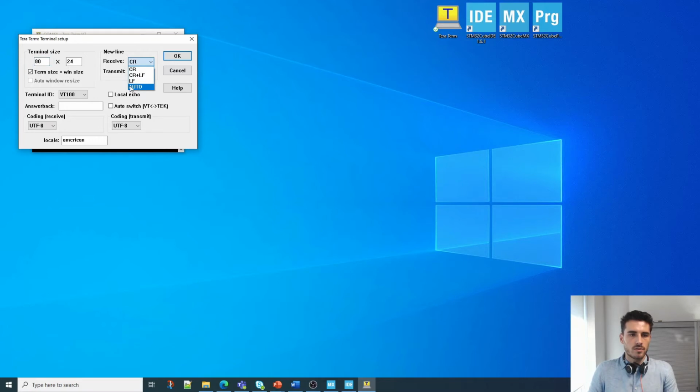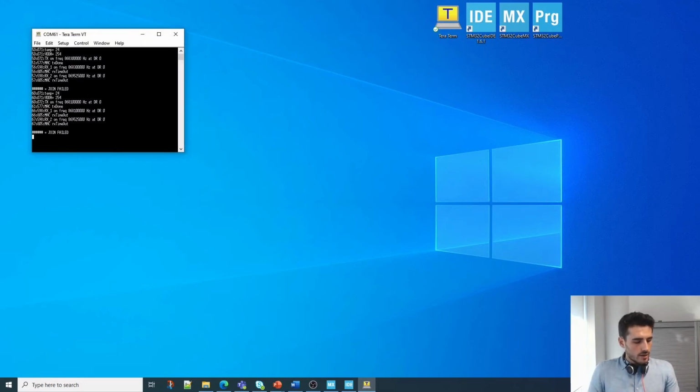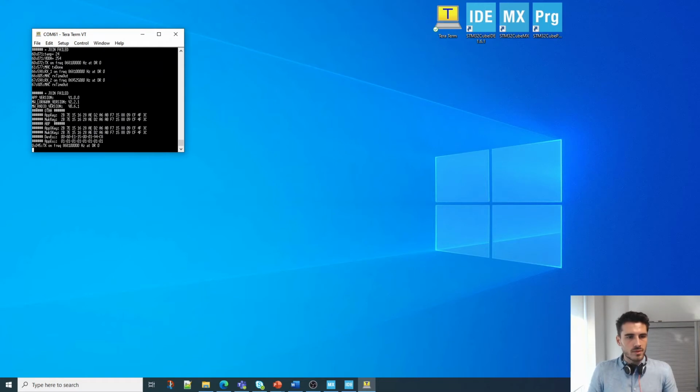So here I use auto. It's a no-brainer. So yeah, just do that. Otherwise, the new line might not work sometimes and you have just weird logs, so just do that. And now if I reset my board, this is what I see.